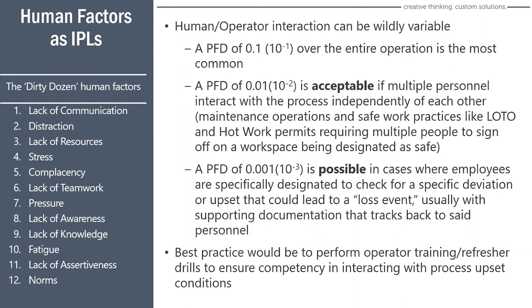And so even in our example, we say, well, we have a high level alarm, and that's another trigger. And that means the operator has to step in and do another event. And if that doesn't work, we have another automated system that takes the operator out of the picture, and that adds additional control. So just getting back to this, you've got to figure out that the human factor is something that you cannot overlook when it comes to these LOPAs.